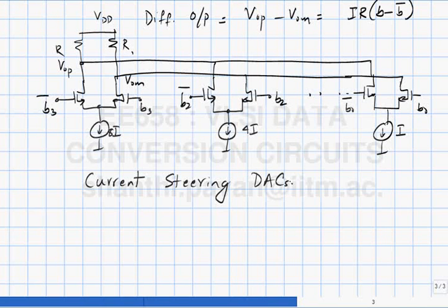And while I have shown B3 and B2 and all that to be logical signals, logical 1 and logical 0, in reality all that you need to do is make the difference between B3 and B3 bar sufficiently large to steer current this way or the other. How much voltage do you need roughly to steer a differential pair? What does that depend on?